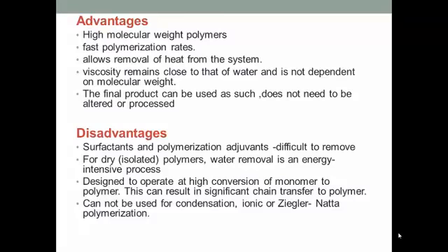A disadvantage of this process is that the emulsifier and polymerization additives are difficult to remove, and for dry polymers, water removal is an energy intensive process. It is designed to operate at a high conversion of monomers to polymers. It cannot be used for condensation, ionic or Ziegler-Natta polymerizations.